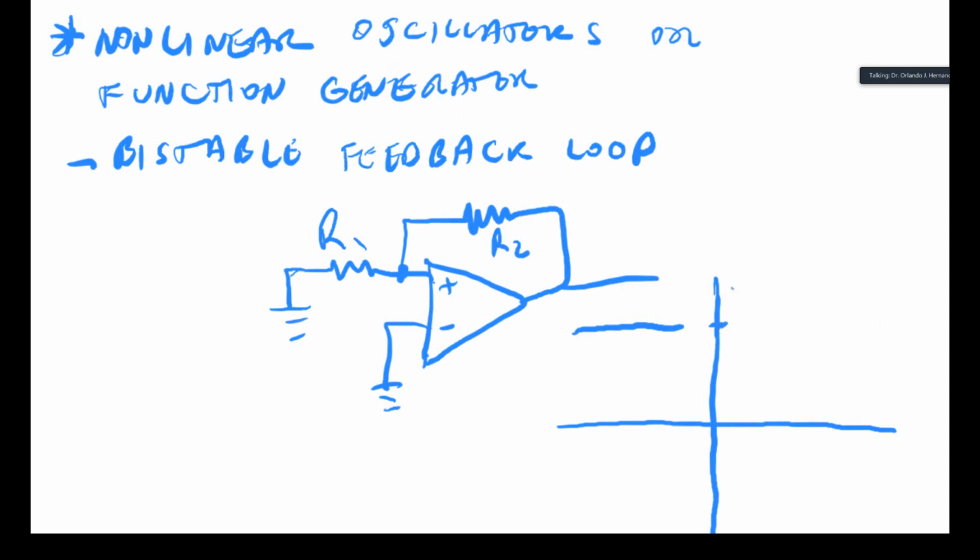let's call it L plus, and of course it's going to be something close to the rail. No op-amp perfectly drives to the rail, but maybe a little bit lower. So this is VO, and this would be the input voltage as defined at this node.